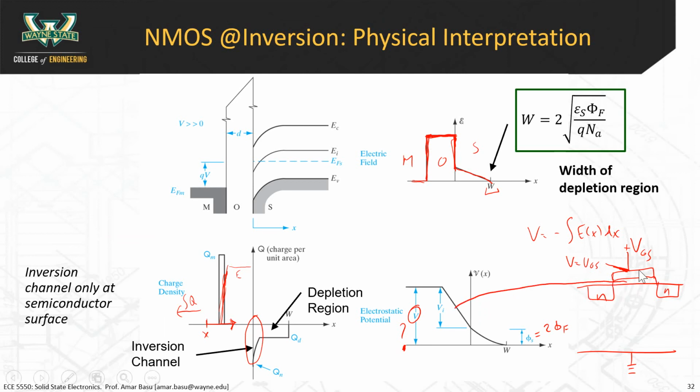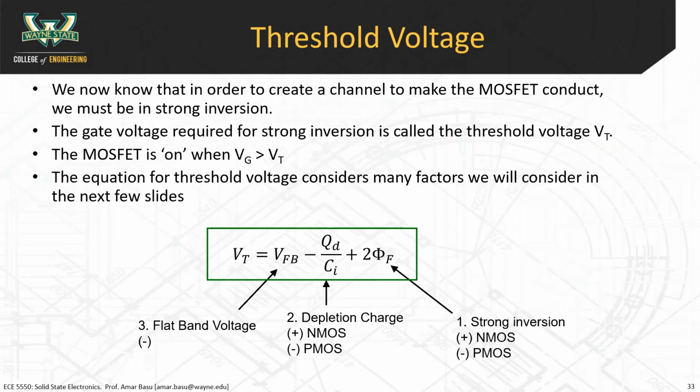All right, so the voltage is maximum up in the metal. It becomes lower and lower as you go across the oxide, and then it drops a little bit in the semiconductor depletion region here. And so by the time you get to here, the voltage is already 0. So most of the voltage drop occurs in this region here that I just highlighted with the pen. So we're just going to calculate what the voltage drop across those regions are. This is the voltage drop across the semiconductor.